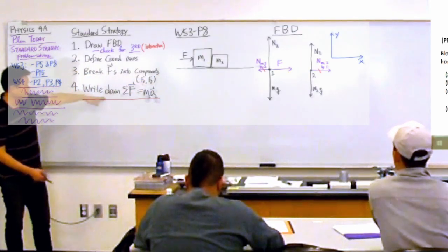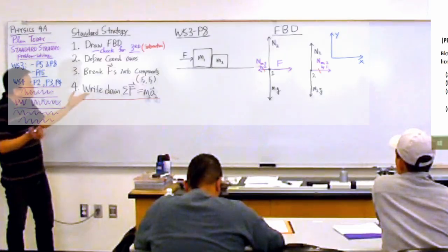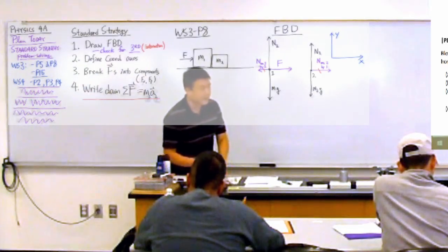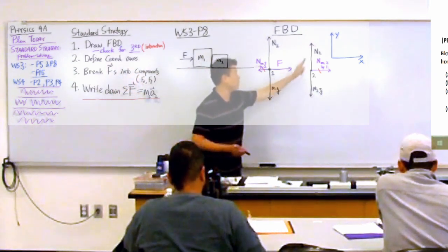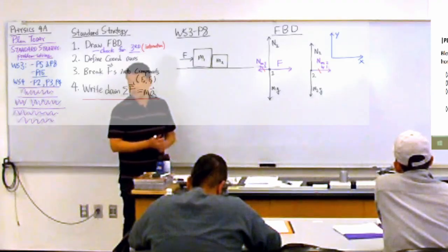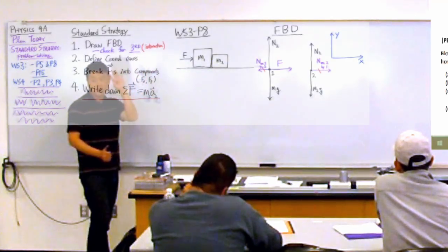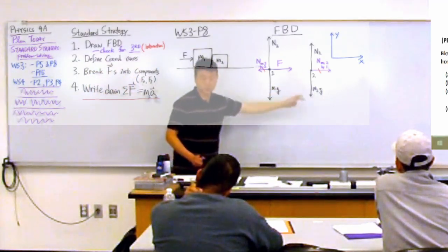And the final step is to write down Newton's second law equations. And, oh, you know what, this time let me just write down all the equations that I can write down. And I will illustrate what I meant by these forces being uninteresting. So you have two objects, and you are writing down Newton's second law equations in 2D. What that means is you have to write down 4 equations total: 2 for mass 1, 2 for mass 2.